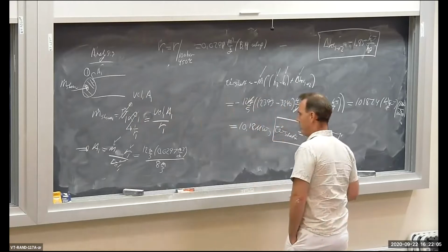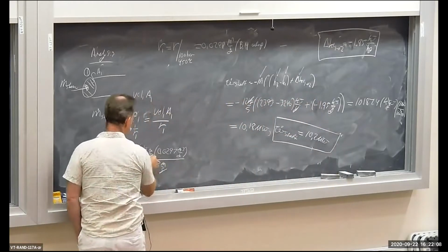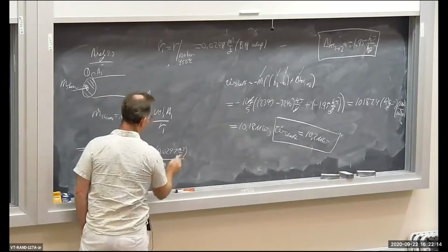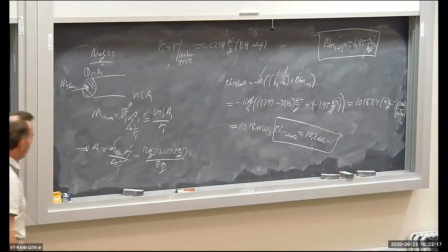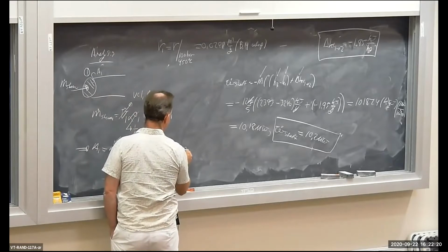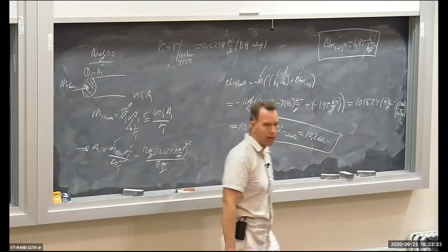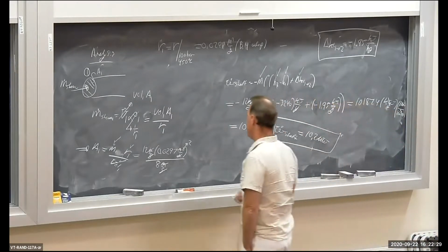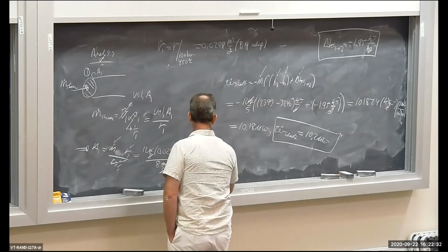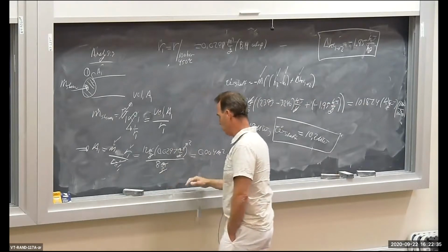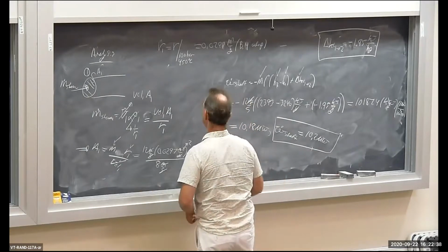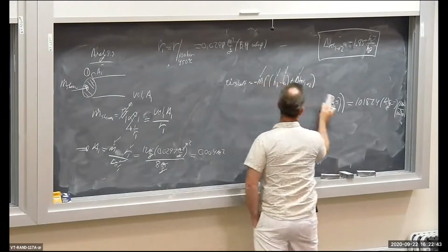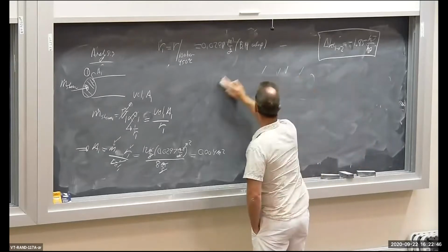Let's look at the units here. The seconds cancel out, meters per second and kilograms per second. The kilogram cancels out in the mass flow and the specific volume. And one of the meters cancels out in my cubic meter per kilogram, and I get meters squared. The result is 0.004 square meters. So the inlet flow area is 0.004 square meters.